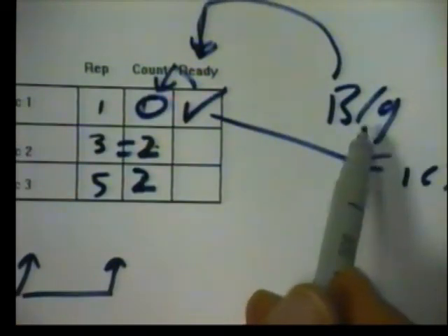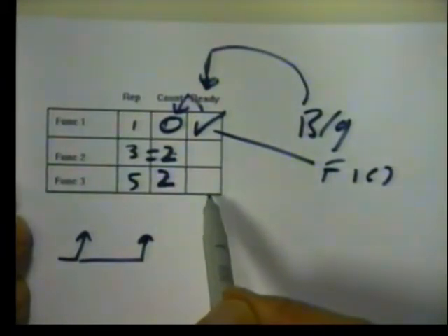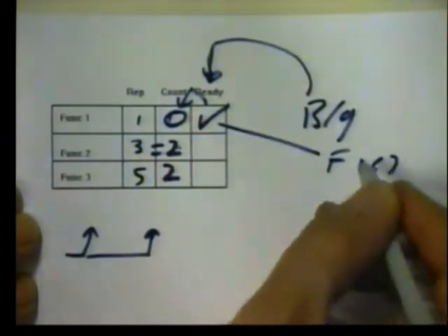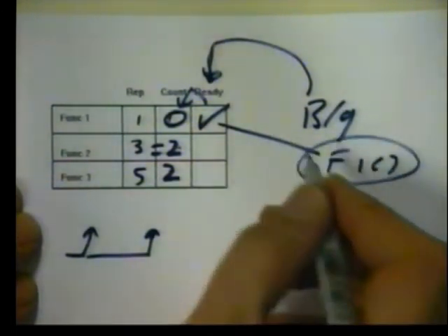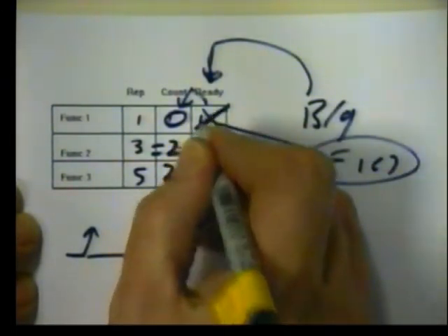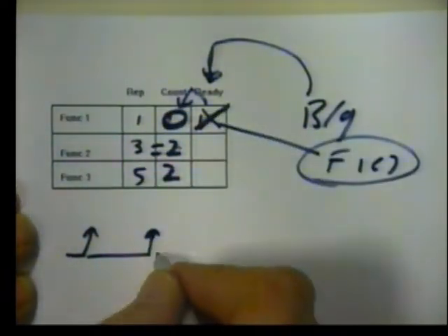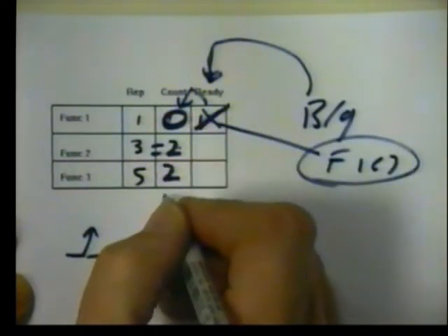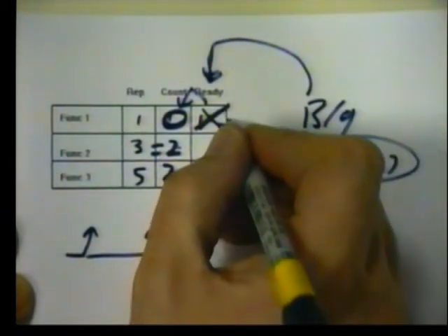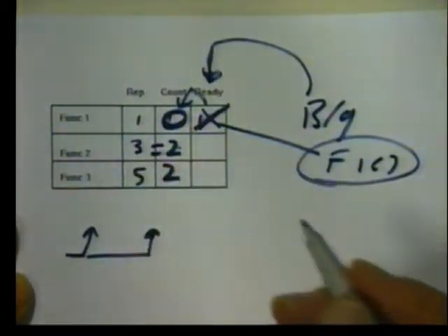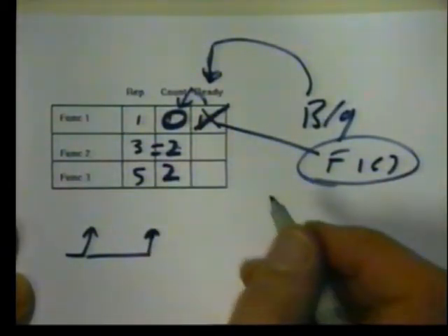The background routine continually scans the ready field. If it sees a function is ready to run, it actually runs it just simply by calling it. It switches the ready field to 0 and resets the counter back to 0. So that means that we have the ability to schedule a function to run, one to run every 100 milliseconds, this ran every 300, this ran every 500.